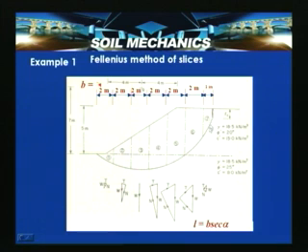That means up to this portion, the base of the slice is exposed. So, this is the soil portion existing here as well as here. We need to consider these properties in this zone, and below this portion we have another soil with C equal to 8 kilonewton per meter square, phi dash equal to 25 degrees and gamma this much. So, these properties have to be considered. By drawing each slice, we can calculate weights W1, W2, W3, W4, W5, W6 and W7, and gamma 1 and gamma 2 are considered for arriving at weight W3 in this portion.